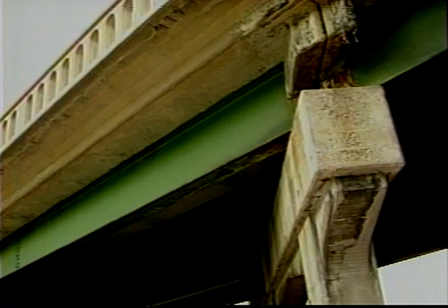Bridge members are highly affected by the environment. However, different bridge materials show different types of deterioration problems. Deterioration of component materials can lead to structural deficiencies. Steel members corrode after significant paint or protection system deterioration. This corrosion can cause substantial loss of the net area of the metal section and thus a loss in strength. Steel members are also susceptible to cracking and brittle fracture, which in many cases is related to the effects of repeated loading or fatigue beyond an allowable level.